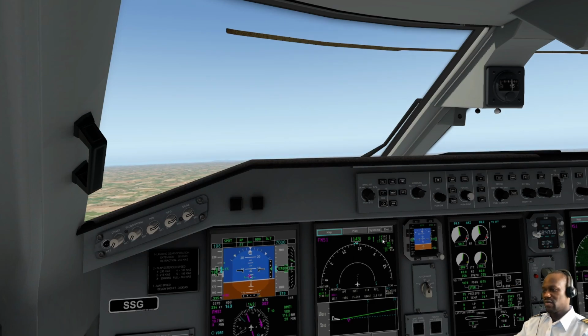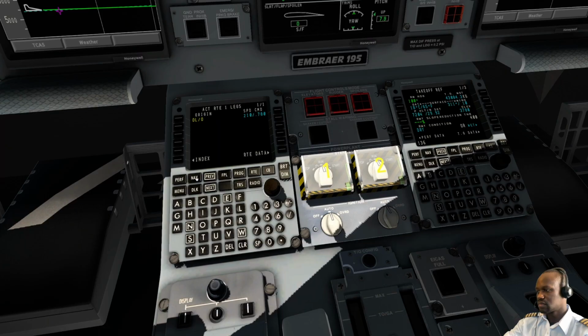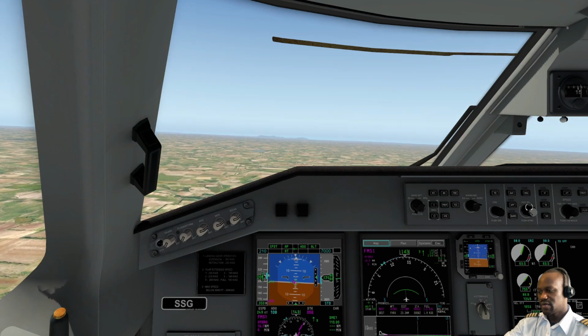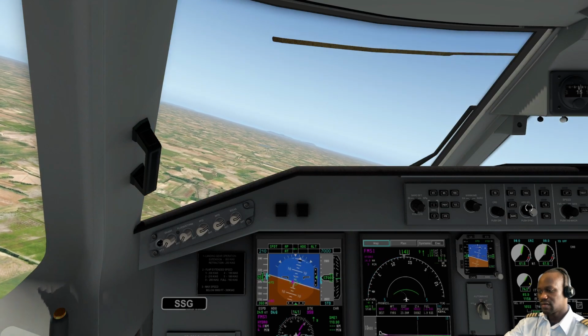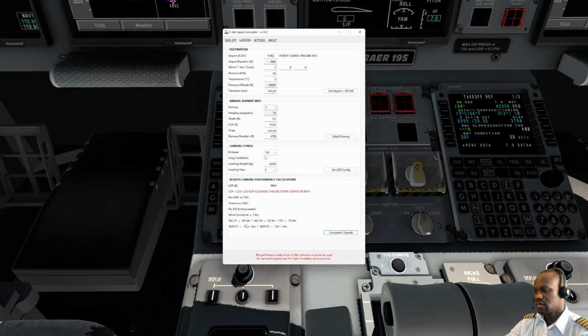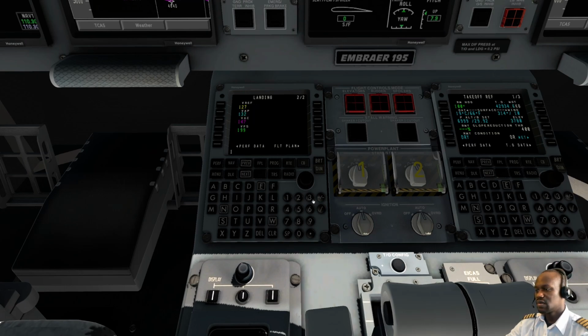Okay, so we're now settled. Speed on thrust, autothrottle engage, autopilot engage. Set a new arrival, ILS, via position Hydro. So you just select ILS initially, turn towards Hydro.